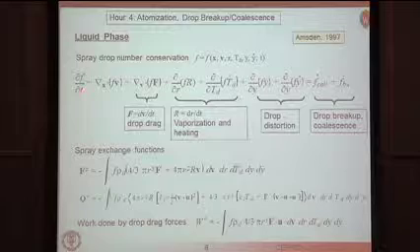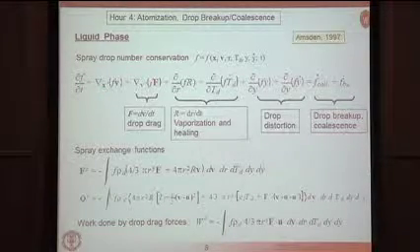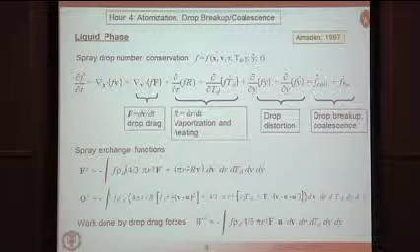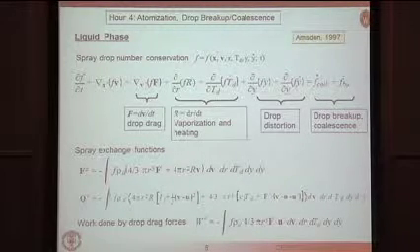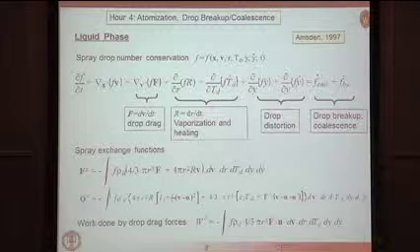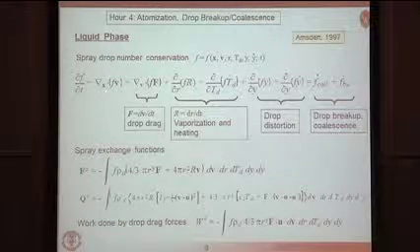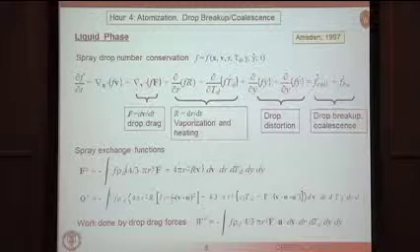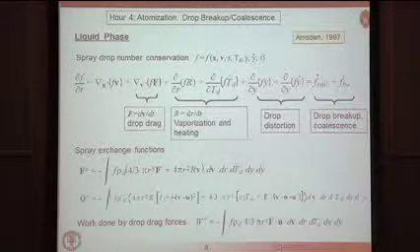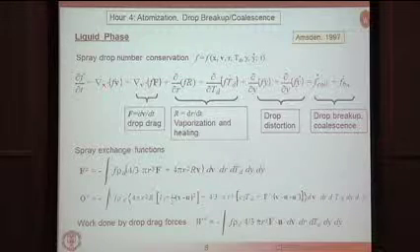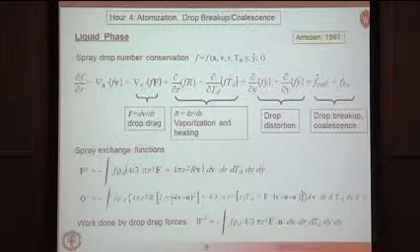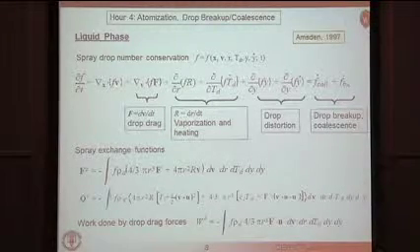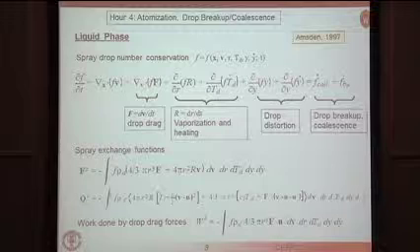So that's why we need to track that as well. Okay, so here's the spray conservation equation. Essentially, it's a conservation equation for the number of droplets, and was proposed by Williams many years ago. We have a time evolution term, and then we have fluxes in the spaces defined by these independent variables. So for example, here, the droplets are moving at velocity v, so we have a convective flux as this distribution function changes from cell to cell due to droplets being convected from one cell to the next.